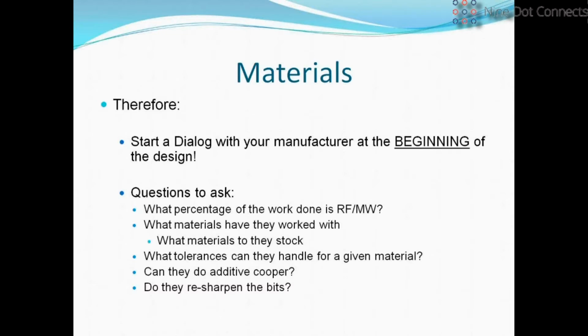All too often, we try to stuff everything onto a single board. So we have a massive BGA that's got 3 mil clearances, or pardon me, 3 mil traces, and we have an RF section with a 19 mil trace on it. If that material has certain tolerances, it may just make it impossible to do the digital. They may say, "Hey, look, with the tolerances we have over here, the best we can do is a 5 mil trace, as it's stretching because the registrations are very difficult to work with."